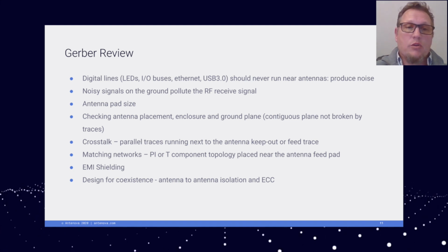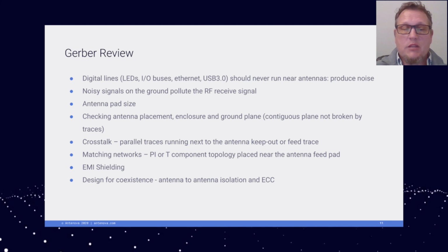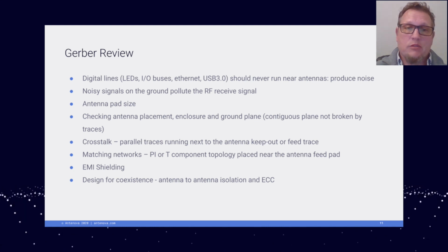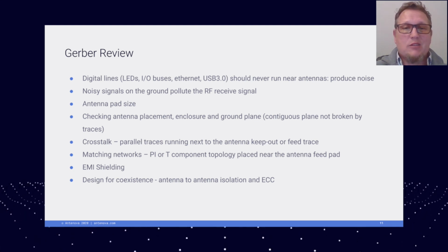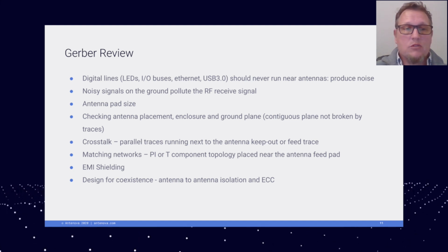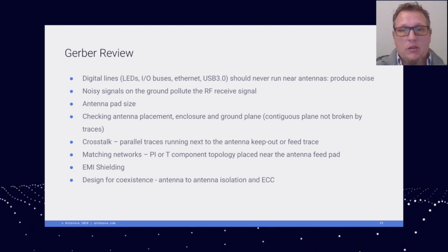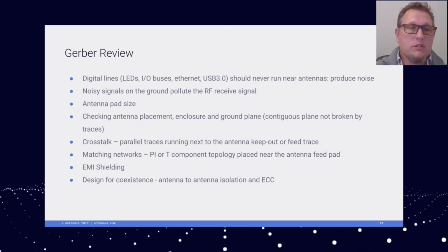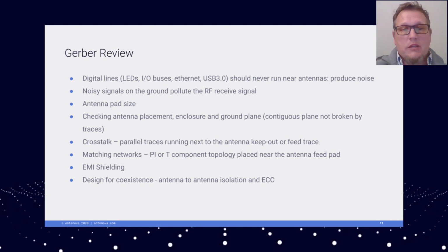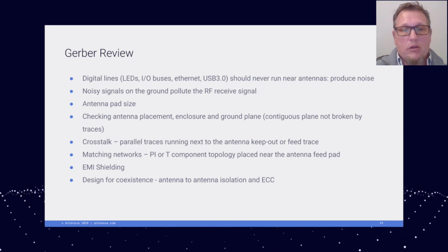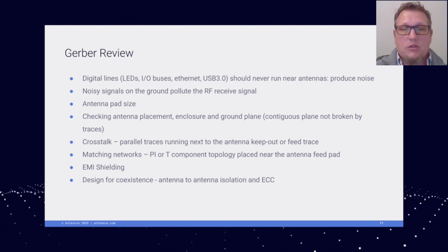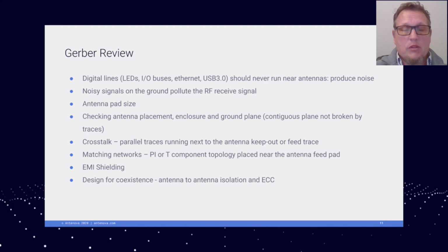At this point, you can consider potting or gluing the antenna to the printed circuit board if your device has higher vibration and drop standards. You want to check to make sure your antenna placement is within a certain distance from your plastic housing so that your housing doesn't hit the antenna and knock it off. You also want to make sure that your ground plane is one solid ground plane for your antenna to operate against. Try not to run data lines near the antenna trace parallel to that antenna feed trace, because parallel lines will couple and you will get noise going into your receiver and degrade the performance.